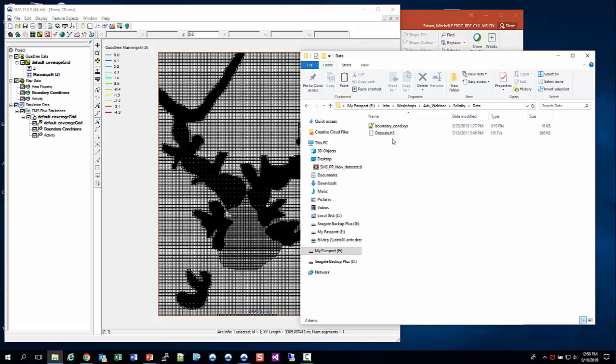I saved it as an H5 data set. And then later on, I read this data set into CMS as a salinity initial condition, and then link this file to the model setup. So that's the initial condition for salinity. That's the file.